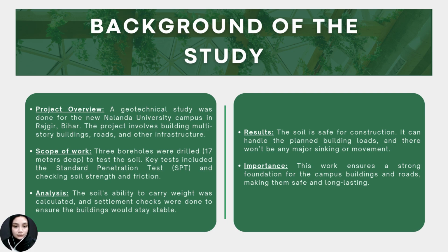To support the project, we drilled three boreholes up to 70 meters deep to assess the subsurface conditions, and key tests, including the standard penetration test, were conducted to evaluate the soil strength and friction. This allowed us to calculate the soil bearing capacity and ensure settlement stability. Ultimately, we concluded that the soil is safe for construction and capable of supporting the planned loads without significant movement or sinking.